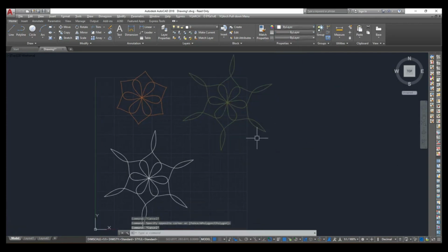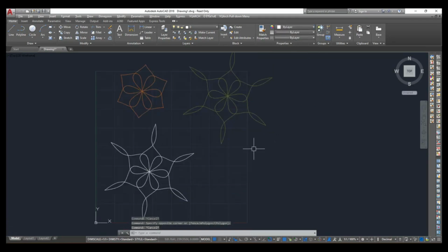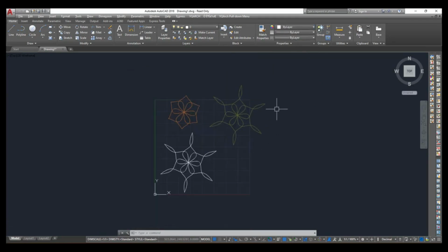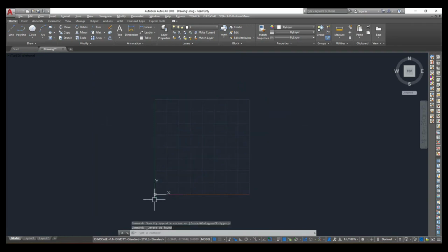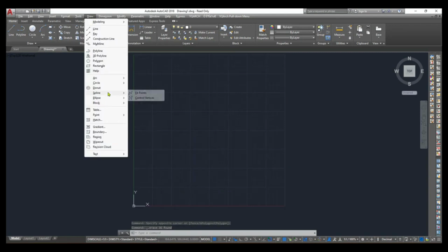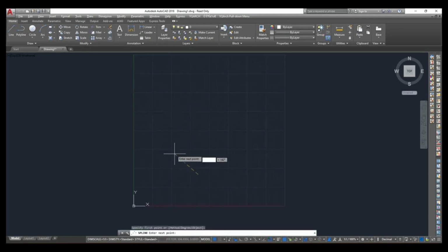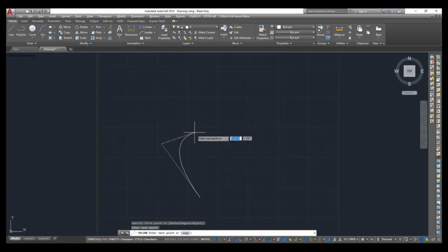So like this way you can implement the spline command while doing the interior design or door design, anything whatever you want. Just I am selecting all by pressing Ctrl A and then delete. The next method is spline with CV. It is also same, but just I am getting the extra amount, extra smoothness from the clicked point, like this. So you can repeat the same process as like earlier.